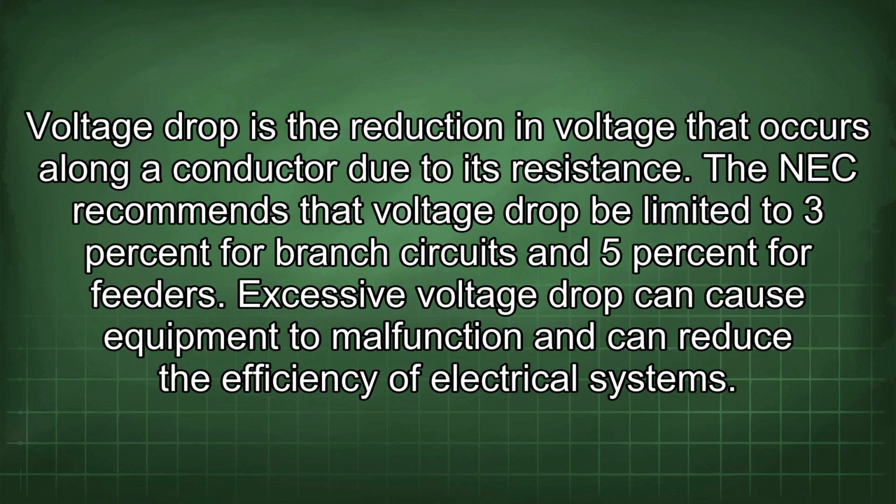Voltage drop is the reduction in voltage that occurs along a conductor due to its resistance. The NEC recommends that voltage drop be limited to 3% for branch circuits and 5% for feeders. Excessive voltage drop can cause equipment to malfunction and can reduce the efficiency of electrical systems.